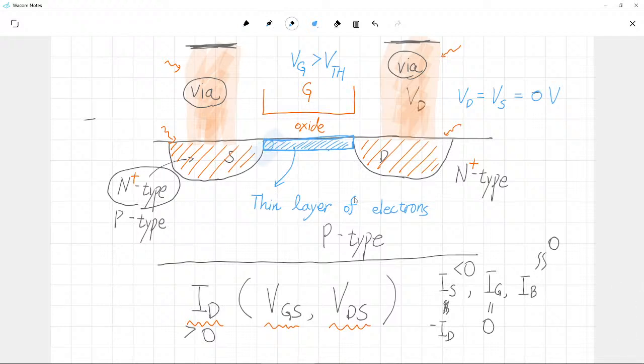Okay, so what I'm asking you is, please think about electron density at this part and that part and another part. Now I'm showing you 3 different points, so can you see it clearly? So I'm showing you the point which is closest to the source and which is closest to the drain and the middle of the channel. So this region is called a channel. So channel means the channel connecting the source and drain. So this part will be called a channel.